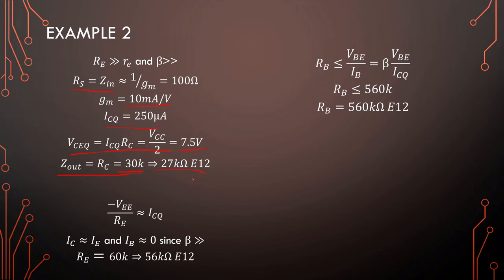For a test or something, I would be happy with this. If I need to put a reason why I go with 27, that is closer to the 22 kilo ohms that we have as our load, and that will actually promote maximum transfer to the load a little bit better than a 33 kilo ohms. So that would be my reasoning for choosing the smaller value.